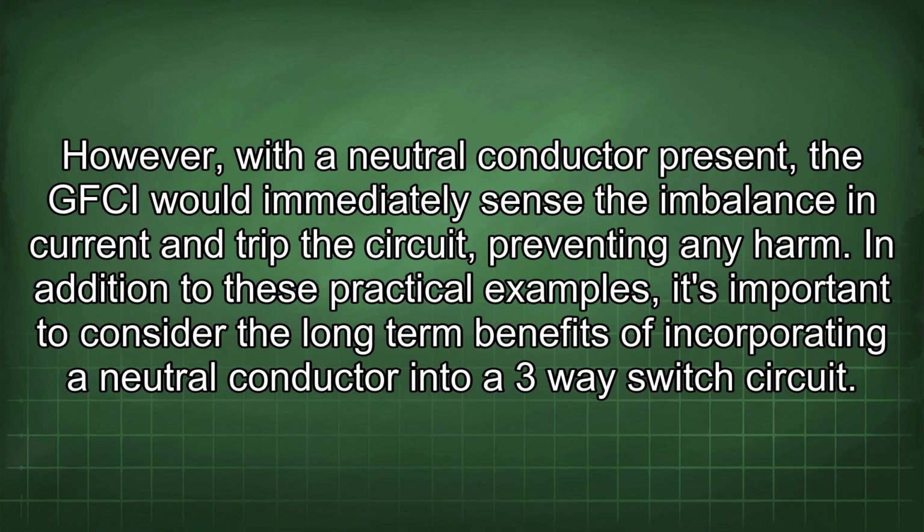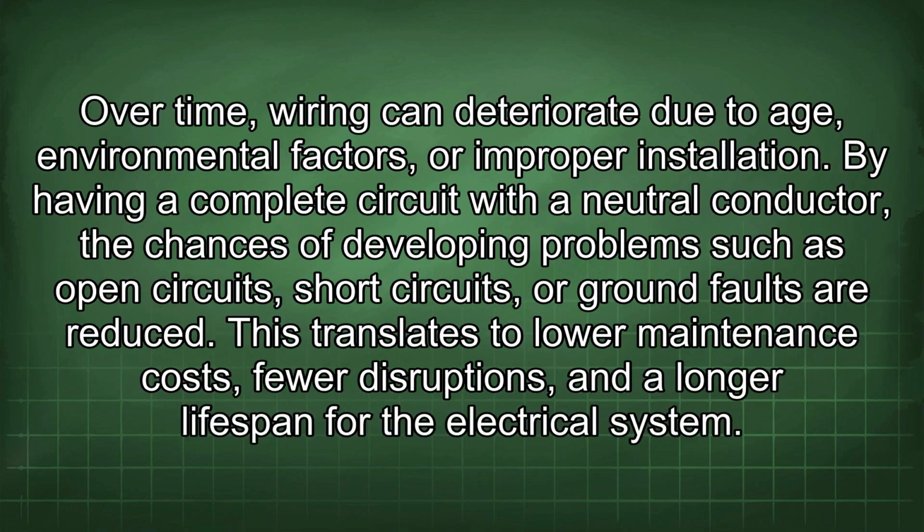preventing any harm. In addition to these practical examples, it's important to consider the long-term benefits of incorporating a neutral conductor into a three-way switch circuit. Over time, wiring can deteriorate due to age, environmental factors, or improper installation. By having a complete circuit with a neutral conductor, the chances of developing problems such as open circuits, short circuits, or ground faults are reduced. This translates to lower maintenance costs, fewer disruptions, and a longer lifespan for the electrical system.